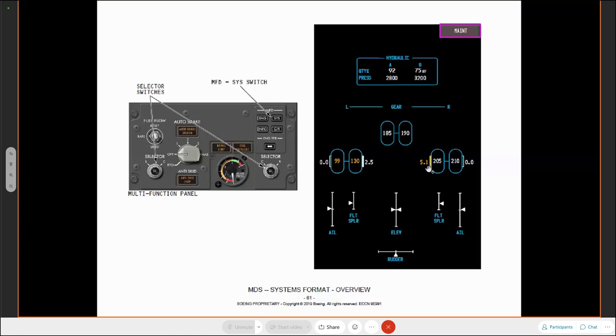As the temperature starts to increase, it gets to a threshold where it no longer becomes the warmest brake, but it becomes the hottest brake. So in that case, we change it to amber. Again, another cautionary indication. You can see here, this one says 2.5 and it's filled in white. That's just telling me that that is the warmest brake of those two, just to highlight it. That's all it's doing. There's no brake fans, so there's no way of rapidly cooling these down.